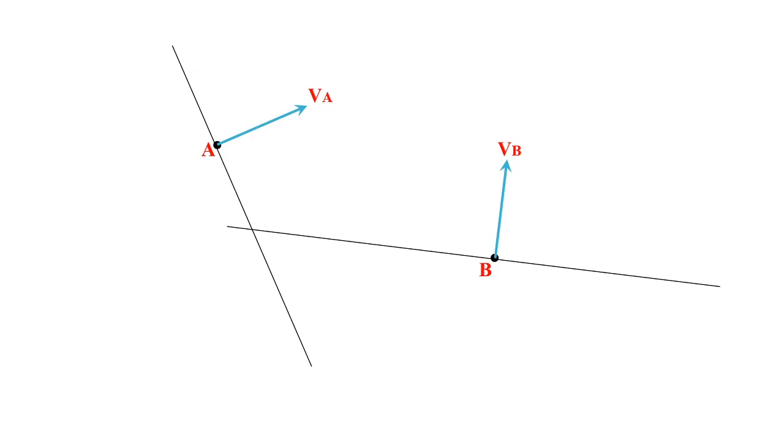So this common point I will define as I, or the instantaneous center of both A and B at this instant. Clear? So now we can say I is a point at this instant such that it is a center of rotation of both A and B. Simple. This is valid only for this instant. So I is a center of rotation of A and B. So we can say I is the instantaneous center of A and B.